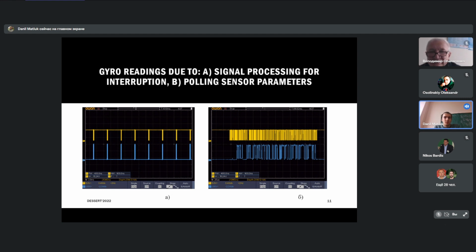The gyroscope readings are discrete values. They were integrated by the microcontroller to determine the angle of deviation from the initial position. The method fully mimics the operation of the sensor without loss of data accuracy and gives a less costly quadrotor configuration. If needed, it is possible to increase the number of devices using free contacts of the microcontroller without loading its memory, thereby simplifying calibration in case of orientation error and quadrotor flight stabilization.